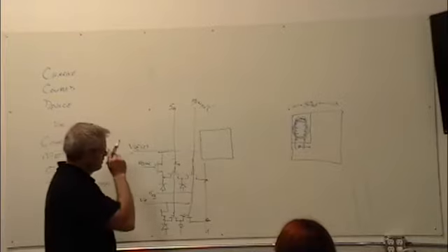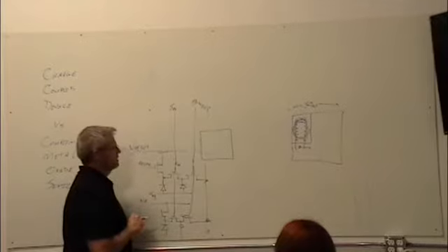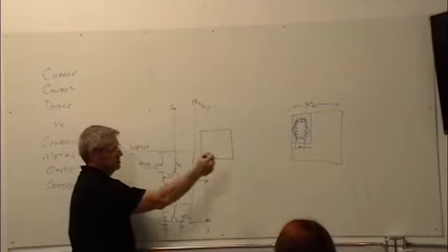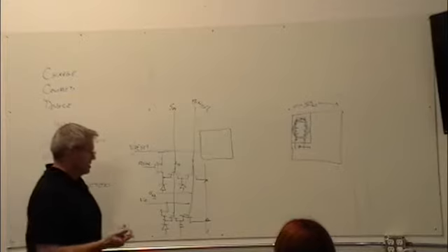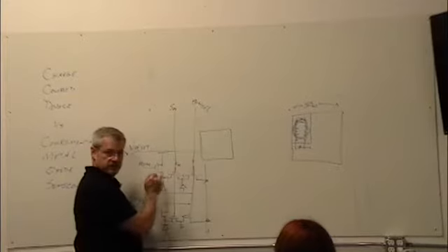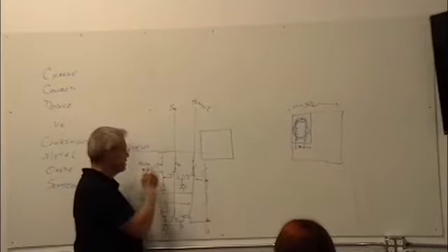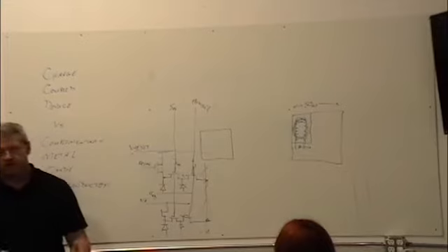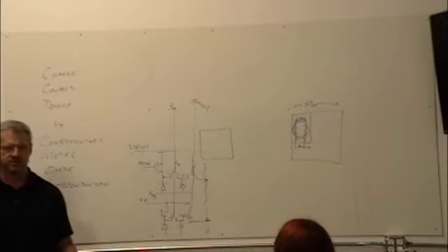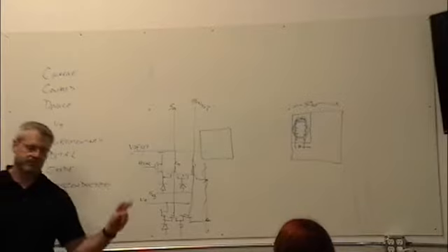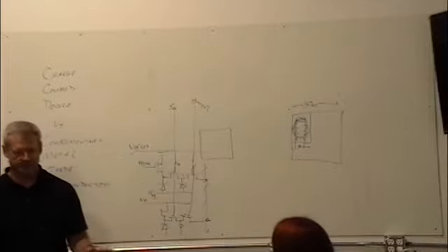So now you start to see some interesting things that happen. The first is, we talked about before, you've got very small fill factor. Second thing is, every one of these is a noise source in your signal chain. There's some resistance here, there's some resistance in the wires, any thermal noise. Traditionally, CMOS is inherently noisier than CCD. If you want to take a good picture, you use a CCD because it's low noise.